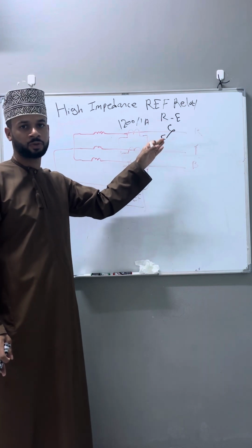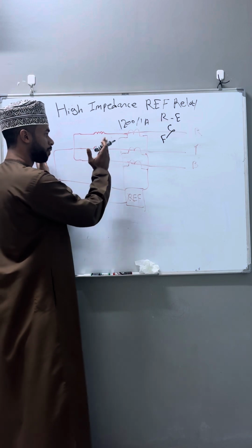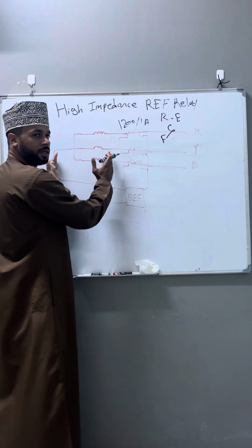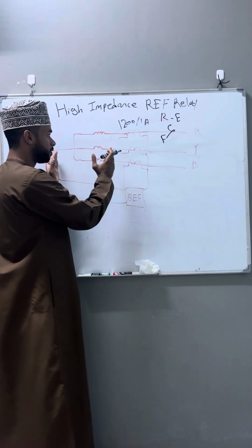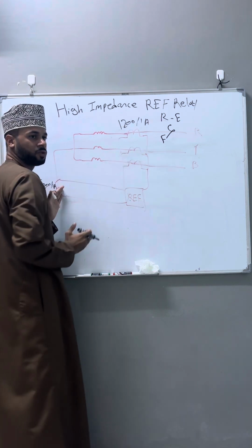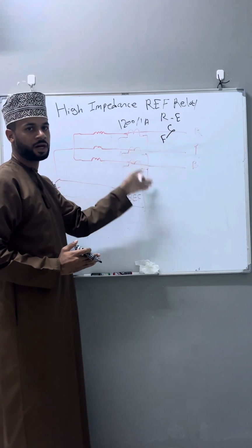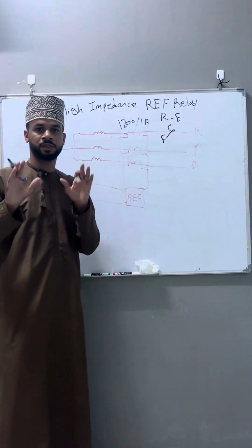So the REF should be what? It should not operate, right? Because I need the REF to operate only if the fault happens in zone. What does in zone mean? It means the location between this phase CT and neutral CT. Any fault outside of these CTs, the REF should not operate and should be stable.